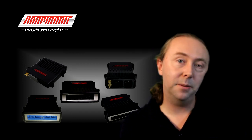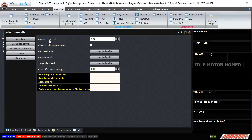Now I've just got 2 final settings which are really basic. One of them is the minimum duty cycle. So if the value that the ECU calculates after everything is below this value, it'll be clipped to this value. The reason we have this is that some idle valves actually become non-monotonic below a certain duty cycle. So for example, at 50% you'll get a certain RPM, at 40% you get a lower RPM, at 30% you get a lower RPM, at 25% the RPM is a bit higher, and at 20% it's higher again, up to 0%, where it's the same as at 50%. So this obviously makes doing closed loop control very difficult. So what we do instead is allow you to select a minimum, where above that minimum it has to be a monotonic function.